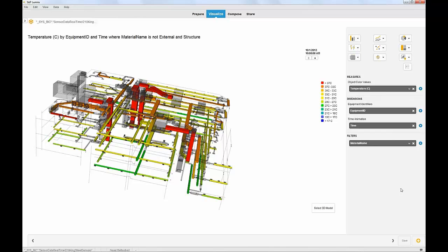If we pause here at 1 p.m., we see there are major differences between one duct and the other ducts. Our duct in question does not heat up. In fact, it shows as being cooler and is nearly 20 degrees cooler than the other ducts on the floor. Resuming the animation, just to double check our model, we can see by nighttime the ducts have become cooler.